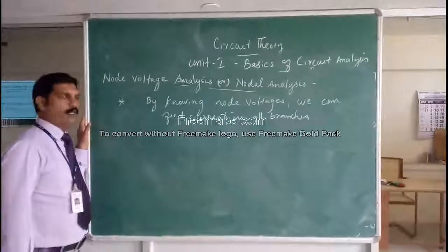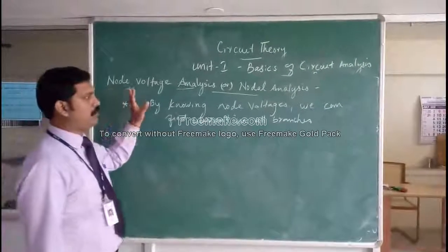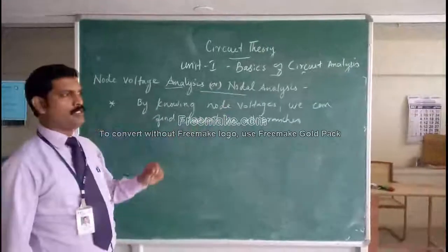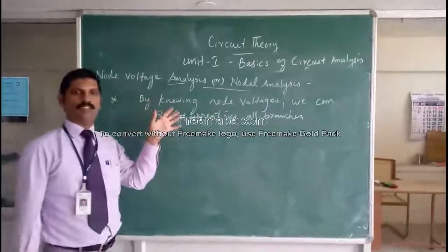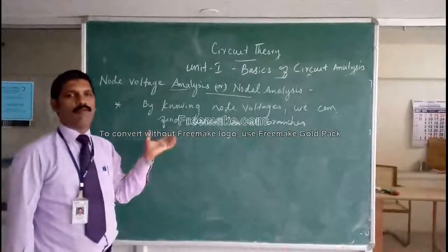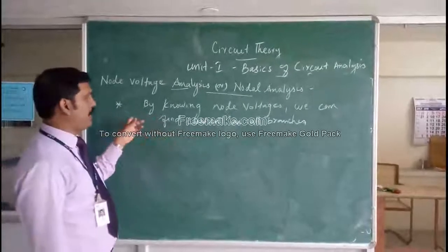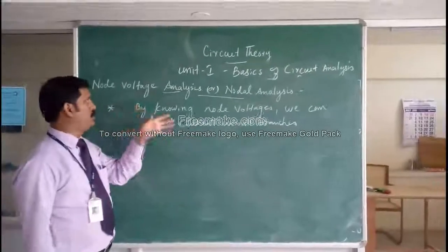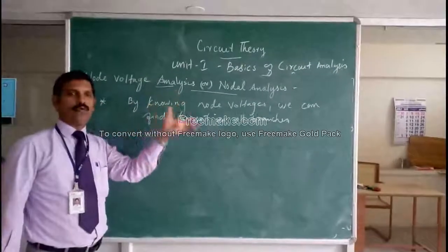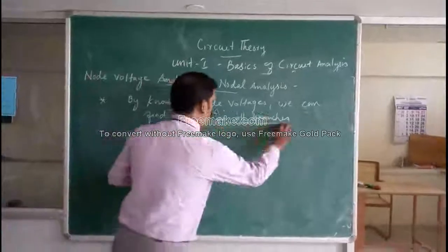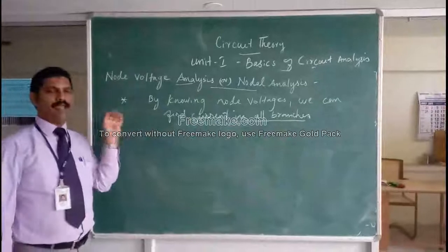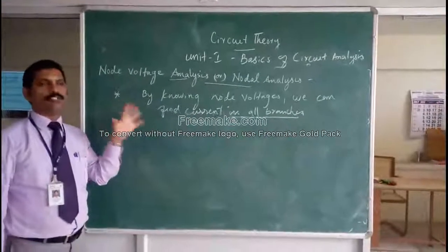The next topic is an important basic topic: nodal analysis, or node voltage analysis. This is similar to mesh loop analysis, where we assume loop currents and then find all the branch currents. Similarly, in nodal analysis we are going to find the node voltages. Using node voltages, we can find the currents in all branches.